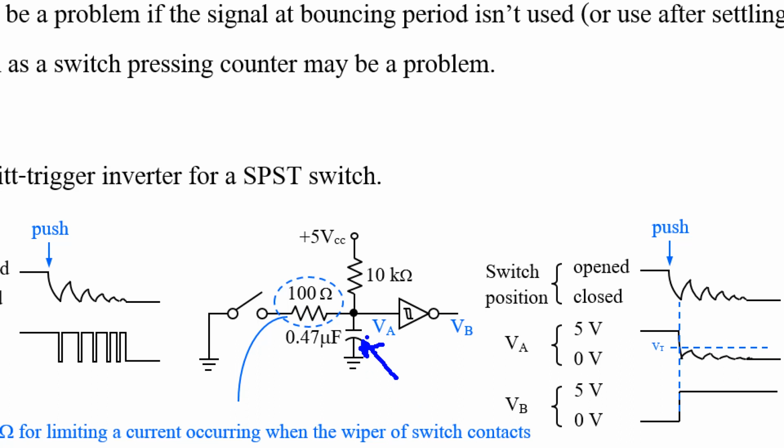You can treat it as an open circuit component. That means at steady state, this point is 5 volt, because there is no current, and assume there is very low current at the input of the logic gate. So this point is 5 volt, or almost 5 volt.